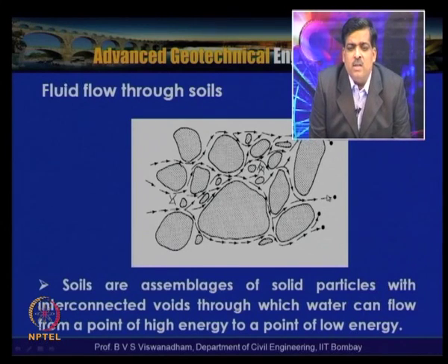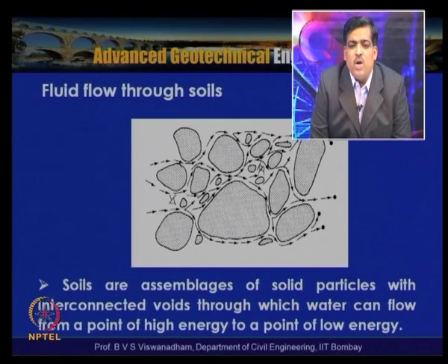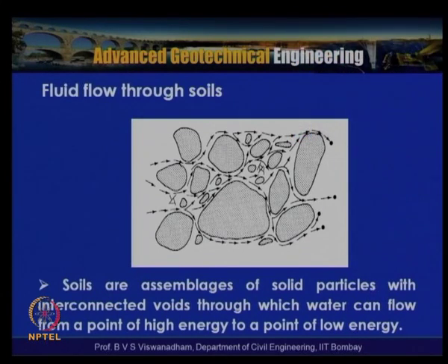So, soils are basically assemblies of solid particles with interconnected voids through which the water can flow from a point of higher energy to lower energy. This study of the flow of water through porous soil media is very important in geotechnical engineering, because it involves the rate at which the water flows through the soil.